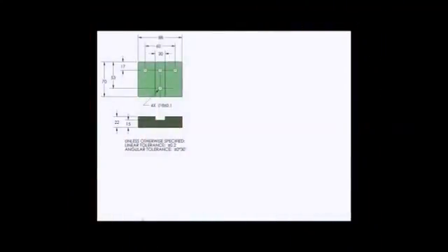I continue to be amazed that there are still drawings out there like the one shown here, where there's no datum features and there's no geometric tolerances, and people actually think that this general tolerance will do the job. I don't know how to set the part up. I don't know what my origins of measurement are. I have lots of features to choose from. And some people argue, well, I know what they want. And sure, you know what they want.